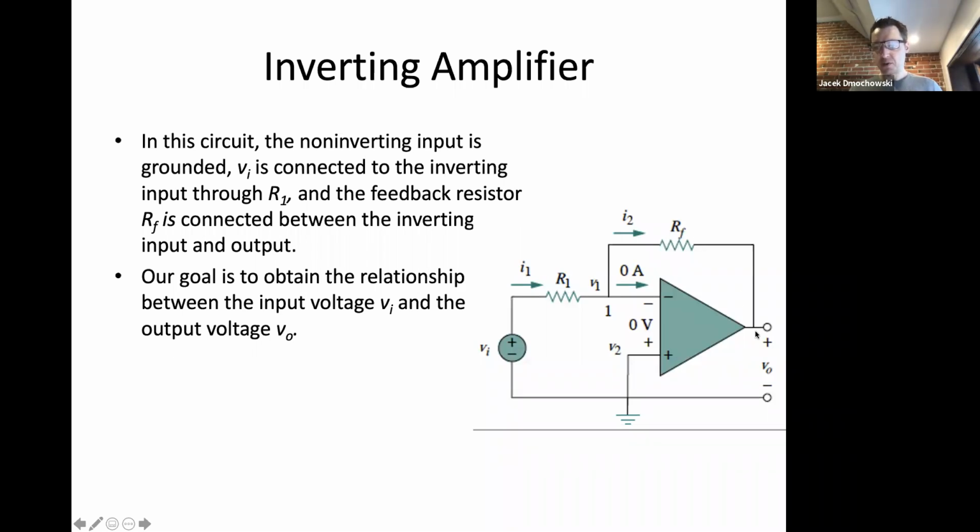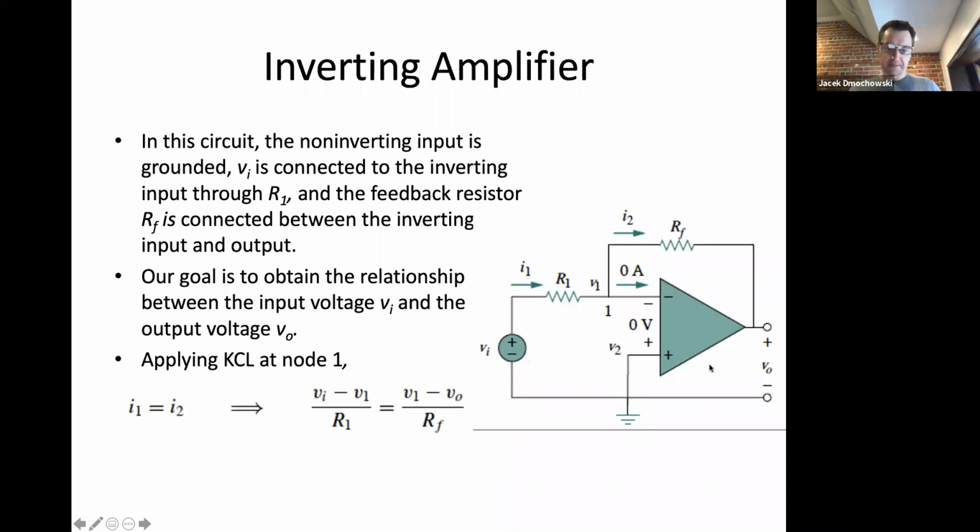It's the resistor between the output and the inverting input. And R1 is the resistor that's connected in series with the battery. We're inverting the input, which is VI. So V naught is going to be equal to negative RF over R1 times VI. So you're inverting the input voltage. This is what you plug into the op amp, and this is what you get out of it.